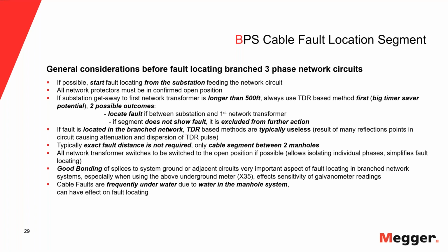So another thing that's very important, all network protectors must be open, must be confirmed open, because I cannot have feedback from network transformers to the circuit I wanna fault locate in. Most of the time today that is done via SCADA operations. So in the old days, one had to go out to every transformer and make sure that the network protector actually opened. Okay.